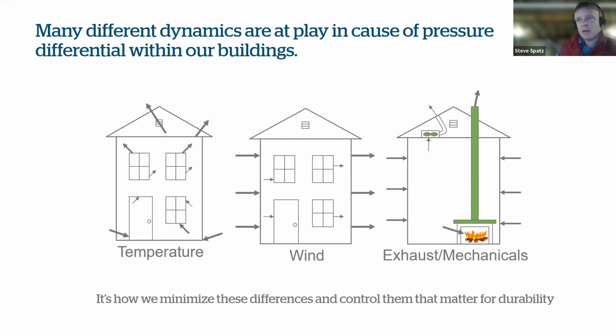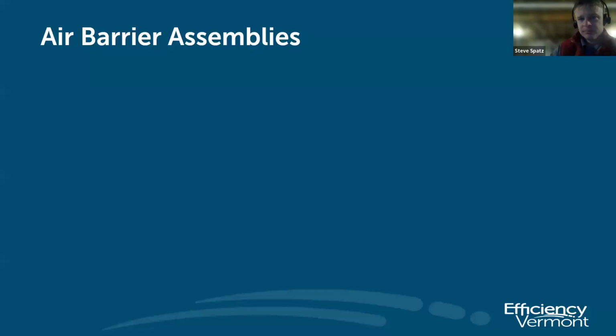Again, thankfully, where we're at now with modern mechanical equipment and codes is that everything at this point is pretty much closed combustion. So the air that's required for combustion and ventilation of those gases is coming directly from the outside, and it's going to be less influenced by pressure changes within the building that could create unsafe conditions. But coming back to it, these are the main fundamentals that impact pressure within a building assembly.